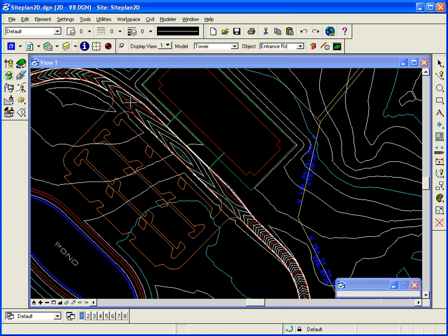You can see that my roadway drains from a high point in the middle back at 0.5% to the right and 0.5% to the left. So my parking lot will do the same. I want a 0.5% slope to each end, and I'll collect the water in each bay and send it off.